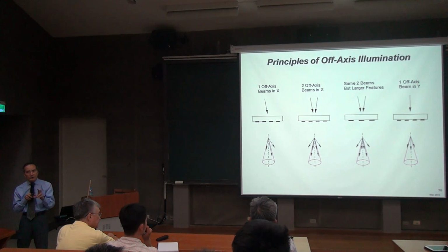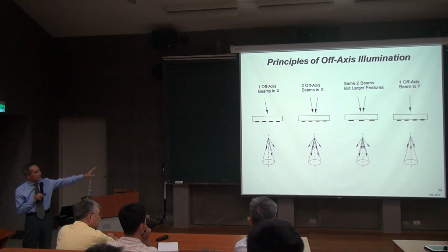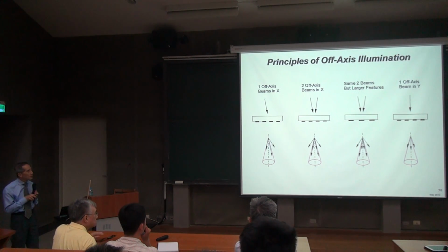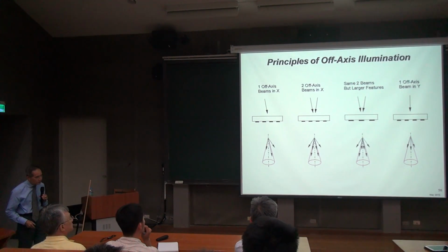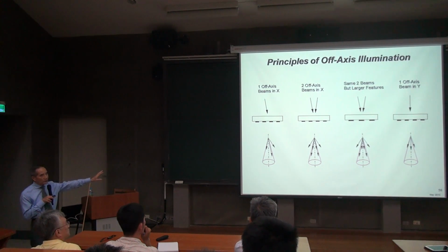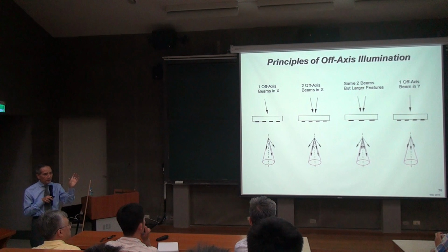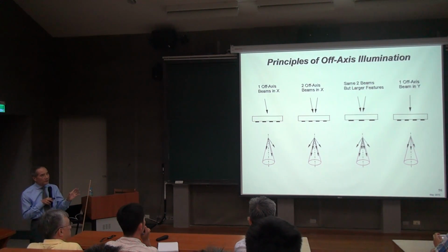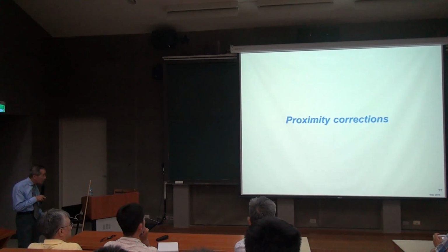Nowadays, when you go to higher resolution, you don't find any on-axis illumination. Everything is off-axis illumination. Okay. And people also play with this too. It's optimal. It's no longer that simple. You have many different vectors to optimize for the specific patterns you are interested in. So it becomes very sophisticated, and also it becomes quite costly.